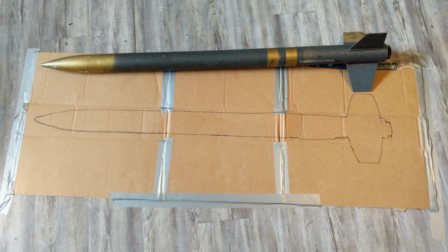In this experiment, the center of mass and center of pressure were approximately found using simple techniques. These experiments were based off of the basic principles of each point. First, the center of mass was found by tying a string into a slip knot and putting the rocket in it. The rocket was balanced at a certain point, which was found to be the center of mass. This is based on the principle that the mass is balanced at that found point.